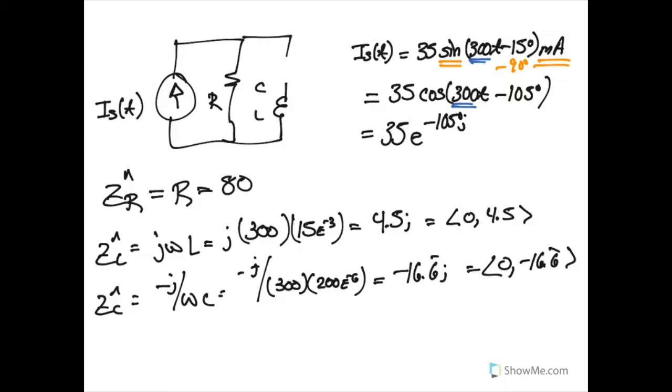So again, we can take out all of our traditional components here and turn them into their phasor equivalents. And now we can perform our original circuit analysis as desired. Again, we want to know what the voltage is across here, points A and B. We can go about our work by finding either the current through the resistor branch or the current through the inductor and capacitor branch, and then multiplying by either impedance.